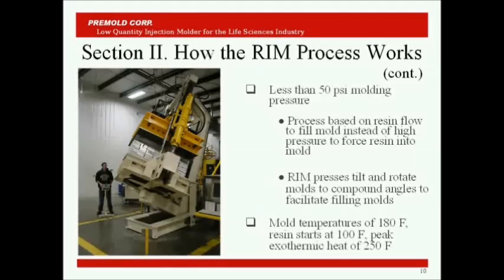Whereas with high pressure injection molding of thermoplastics, you're taking a solid, melting it, packing it into a mold under high pressure, and letting it freeze, usually in a stressed condition. So consequently with RIM, you can mold some large parts or long and thin parts without a lot of hidden stress, or without any hidden stress in some cases. So it makes the RIM parts very resistant to warpage and so on.